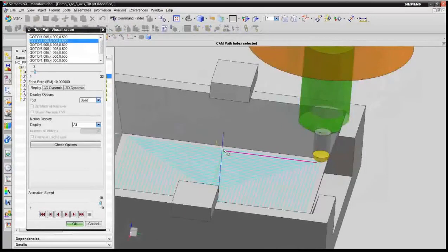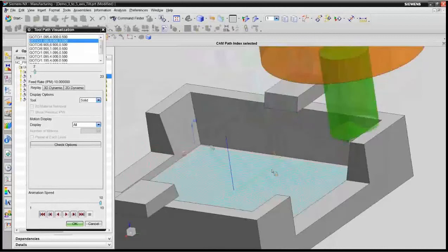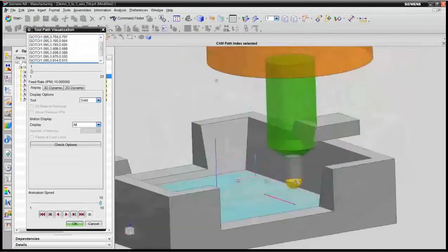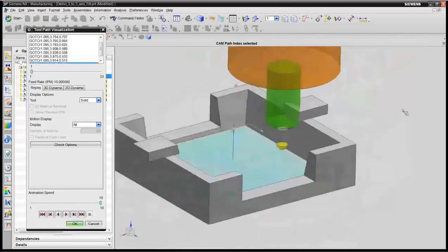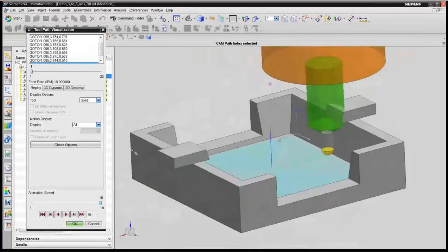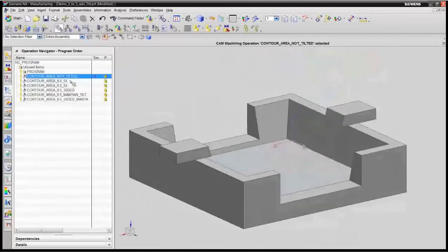Or also, if I come over, sorry, let me get all the way down here. So if we come over here, we're colliding with the clamps also. That is very undesirable. It's kind of detrimental to your machine tool life. But the advantage, we want to use a short tool to make it more rigid. So what we'll do here is tilt this toolpath.